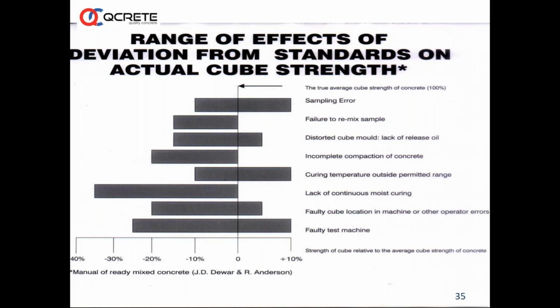What is the potential strength of concrete? Potential strength of concrete is something like target mean strength. So we many times find results totally away from target strength. For example, if the concrete is M20 and the target mean strength is about 26 or 27, here we may have a concrete ending up at 22 or 23 or 21. So a concrete which has a potential to reach 26 or 28 in trials, it has reached say 30 also, but when we take the cubes, it might have reached 22 or 23.